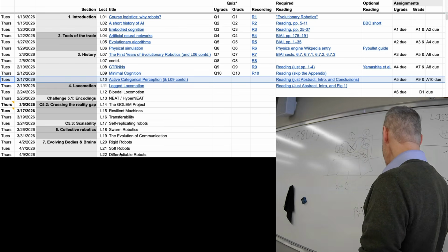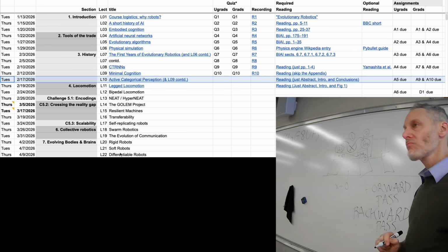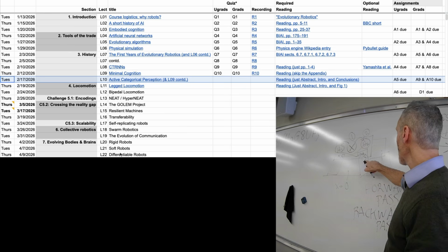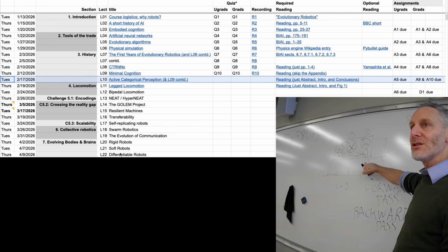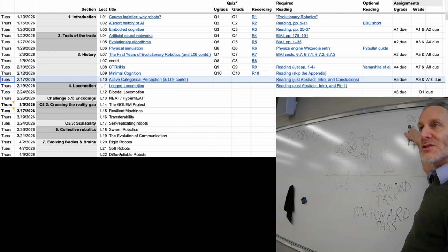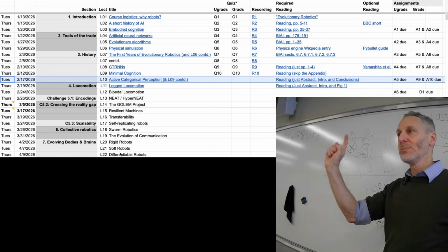The backward pass is orchestrated or run by gradient descent, which is the new optimizer that we're using. What does gradient descent do? Gradient descent starts, step 5 here where we left off, it starts with behavioral loss and works backwards, runs everything in reverse. So where do we go? We go to the motors here. What were the forces at the motors that caused the robot to move in such a way that it suffered this behavioral loss? In essence, what the backward pass does is it assigns blame.